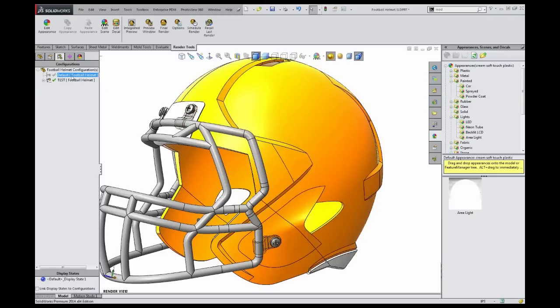And what you'll see by hitting no, I have unlinked display states to configurations, meaning that the display of this first configuration can be exactly the same display as a second configuration. If I had display states linked to the configuration, then upon the new configuration it would have just started off fresh. If you don't know about display states, they're very similar to configurations. They're just controlling, rather than physical properties, sizes, and things like that, appearance properties.